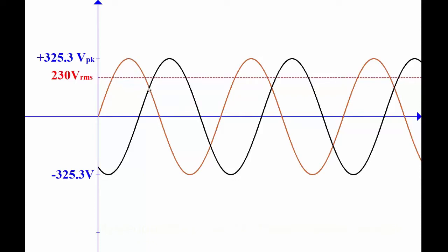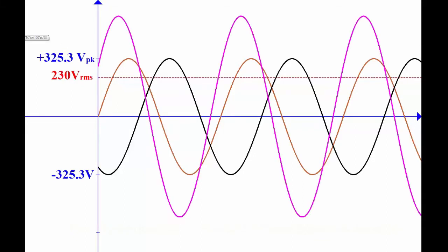We're not just adding these two together, because at this point here that is maybe round about 150, 160 volts. If you added, you would expect a value to be about 300, 320, which is not what we're doing. What we're doing is we're finding a potential difference between these two voltages. Okay, so what we end up with is indeed this one here. This pink graph here shows you the line voltage. Now, yes, those levels are much higher.